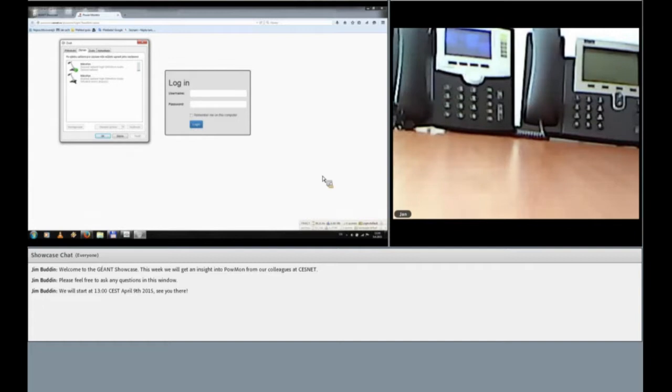So we are prepared to test IP phones for this case. The PowMon software will manage the powering of these phones. The software consists of 2 parts. The first one is a web interface, and the second one is a script which, at 1-minute intervals, polls the device and sets the wanted powering state for the selected object.